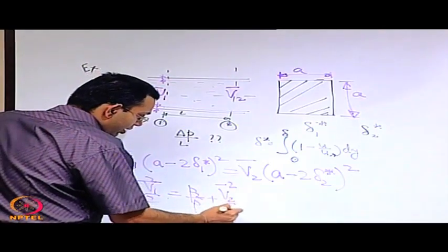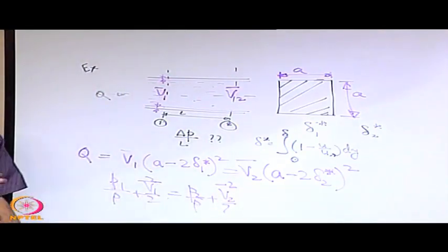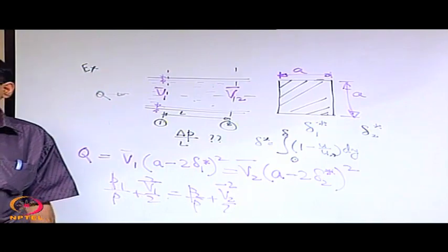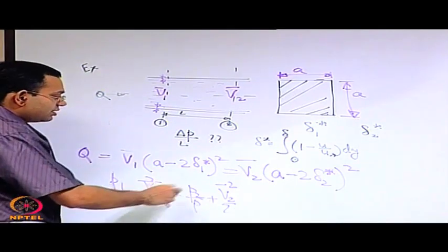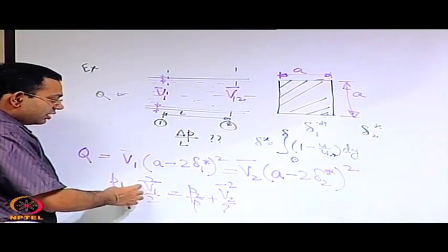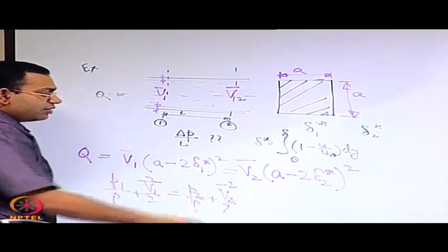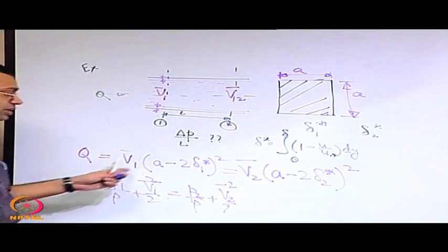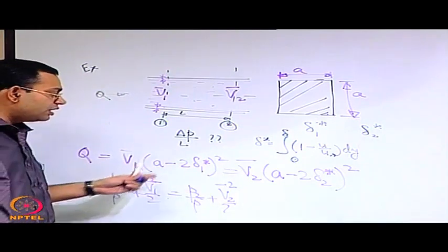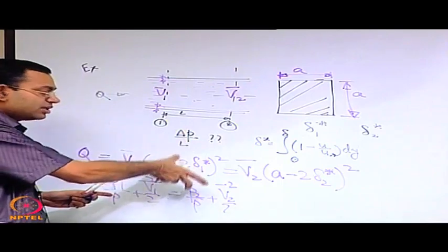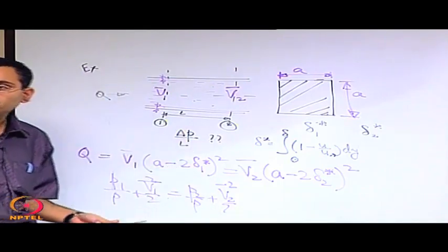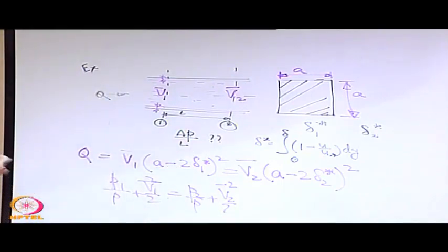See, these P1, P2 are not very accurate or local P1, P2, these are sort of average P1, P2 over a section. But if you get these ones, then you will see that you may write it in terms of V1 square and V2 square. You get another expression involving V1 and V2, and depending on whatever is measured and whatever is not measured, by using these two simple relationships you can find out the pressure difference or whatever.